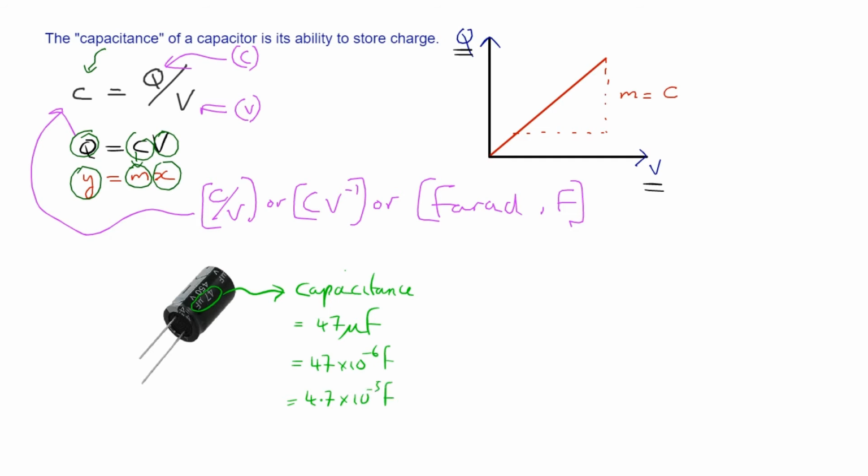That information is given because there's a vast variation in the capacitance of capacitors. One thing we notice is that the value is pretty small, and that's a general feature of capacitors. 1 farad is a huge capacitance, so typically capacitors have capacitances down in the microfarads, even picofarads. There's another figure on there which, even though it's upside down, you can see is 450 volts.